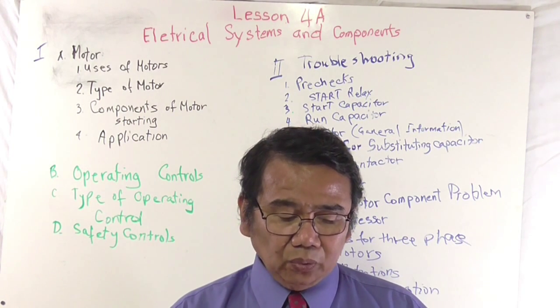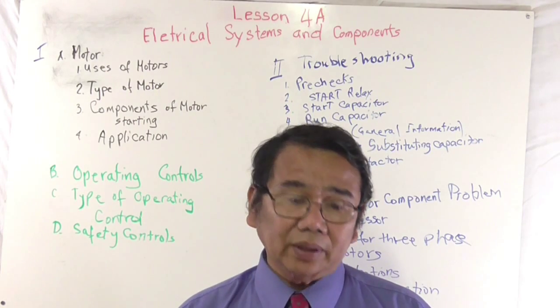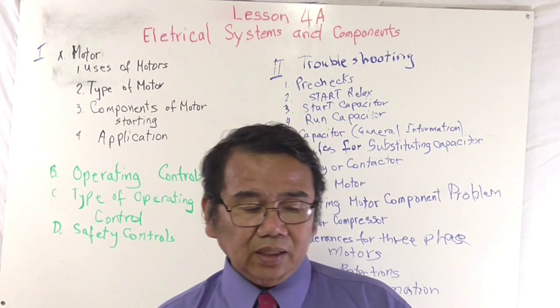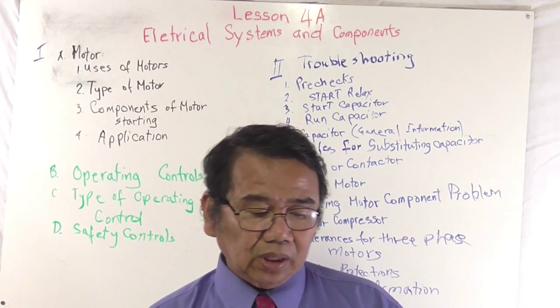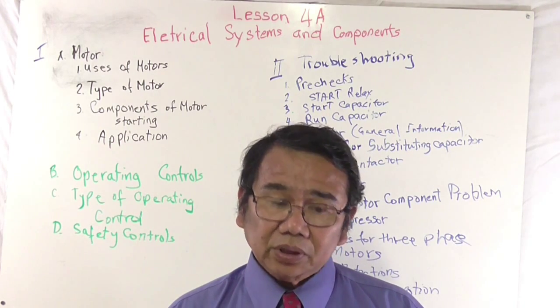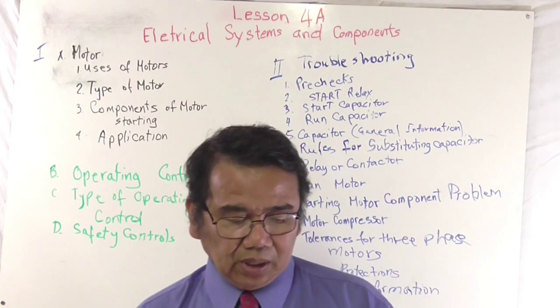And then the one that will not pull in and then its armature: voltage low, shorted coil, and then your armature is sticking. Contacts burned, okay, voltage is low, overloaded, armature sticking.